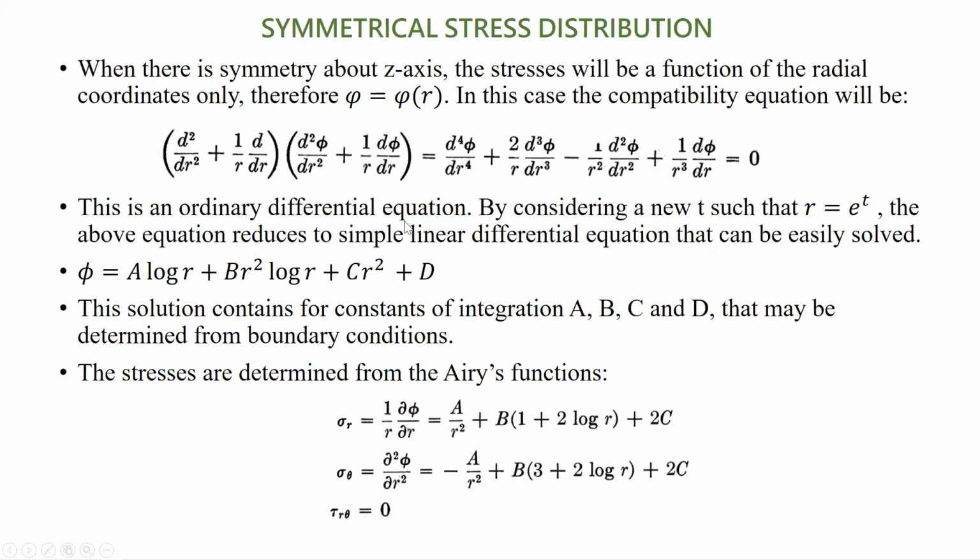Once it's expanded, we come up to this differential equation. It's no longer a partial differential equation, it's a simple differential equation. So any problem with a symmetrical situation, plane stress problem, plane strain problem with symmetry, would have a solution according to that differential equation.